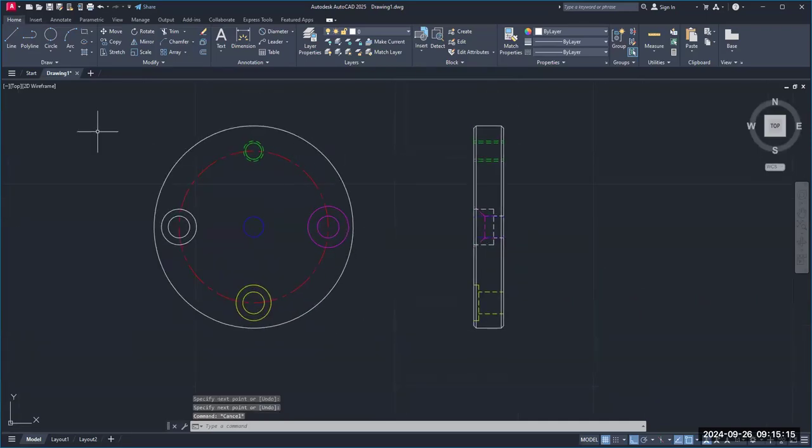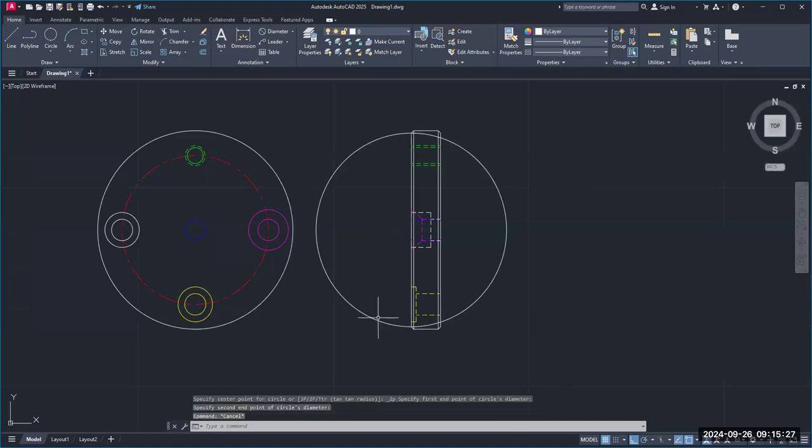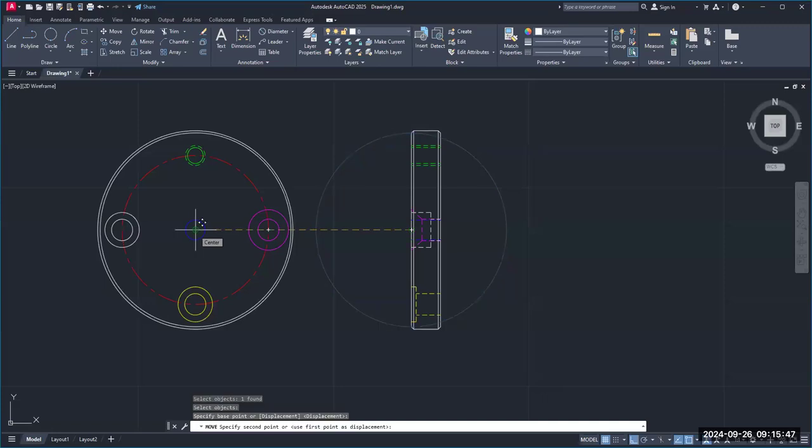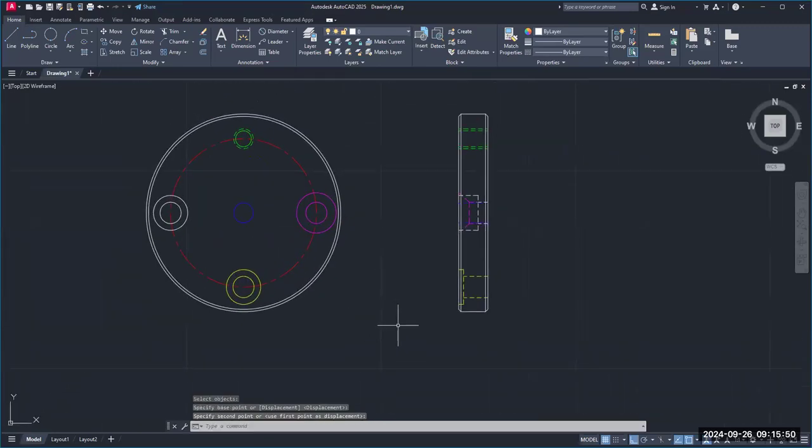Now I have to put the circle, look, circle 2-point, look, 2-point. This is why I did this. I mean, I could measure that line, but I don't need to. I can just use my geometry to get it. I'm going to move, type in M for move, enter, click on the circle, enter, hover around the edge, click, that clicks the center, move over here, click on that center, and there you go. That's the geometry.